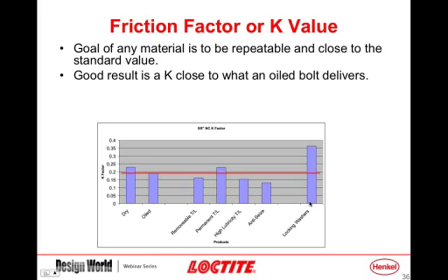We just wanted to have a comparison in here because, again, what we're trying to show in this test was if you take and vary the system, what effect does it have on the K factor that you have? So this first slide is for these specific systems, what did we measure for a K factor? You can see the range of values going from over 0.35 down for anti-seize, which was the low of about a 0.13.